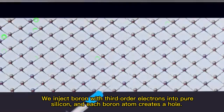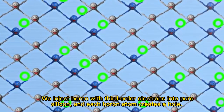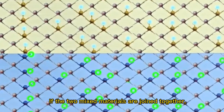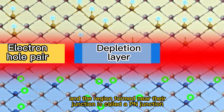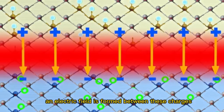We inject boron with three outer electrons into pure silicon, and each boron atom creates a hole. If the two mixed materials are joined together, the n-type electrons will go into p-type holes, and the region formed near their junction is called a p-n junction, resulting in a slightly positive charge on the n-type side and a slightly negative charge on the p-type side. An electric field is formed between these charges.